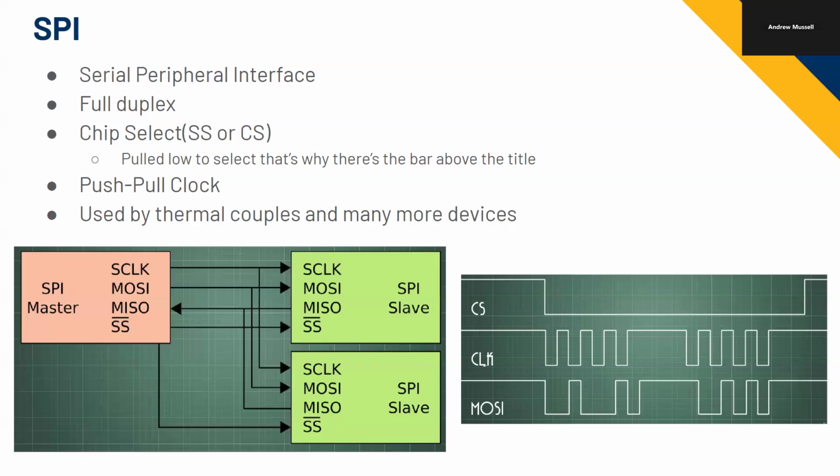Is the clock on all the time, or does it just turn on whenever it needs to send or receive? Once again, it only turns on when you need to send or receive. Like in the waveform on the bottom right, it'll turn off because once again, we don't want to waste all that power switching when we're not communicating.